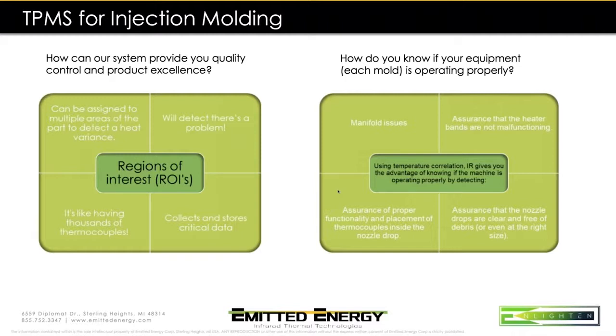What it also does, before it closes off that vent, the first thing it will do is start to make a little gummy type residue. Some people call this defect in the plating world juicing, where the gases condense so much, the molecules condense so much, they turn into like a liquid or a vinyl. And that's what first starts to block your vent and gives you your very first sign that you're going to have venting problems shortly.